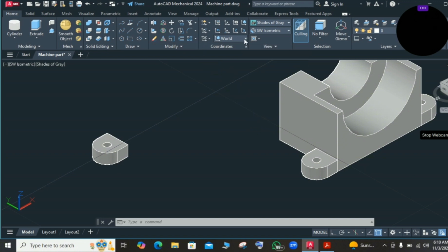So I will turn it to left. Now this is left. Okay, I will use the line command. Start from here. I will draw a line. Activate my auto this time. I will start from here until I get to perpendicular. Enter.